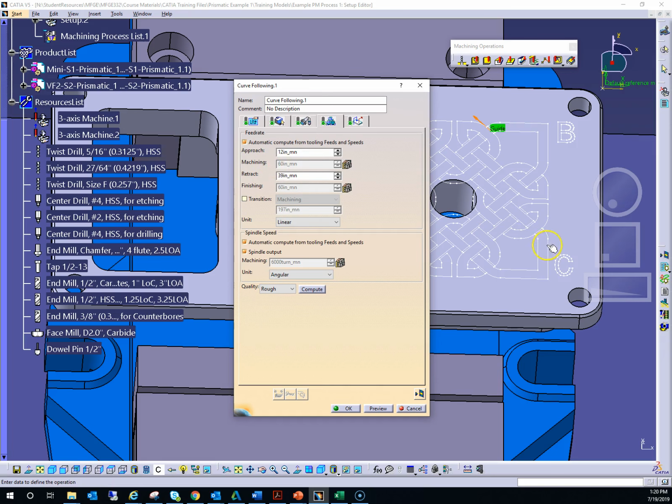So for engraving, which is the tool moving in X and Y as it cuts the shape or the pattern, faster feed rates are acceptable. When you are using a center drill for drilling a hole, of course, 60 inches is way too fast, and that's the reason why we have a separate center tool for drilling, which is very different.